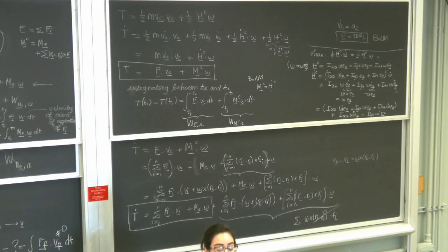Any questions about this? This is important. Yes? If you took your frame of reference to be just those two objects, the issue is you don't get to choose your frame of reference. It needs to be inertial. Velocity needs to be the absolute velocity of the point of application of the force. Relative to the truck, it does no work because it keeps everything going.